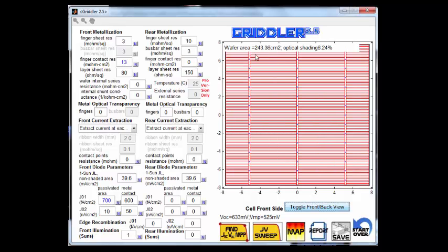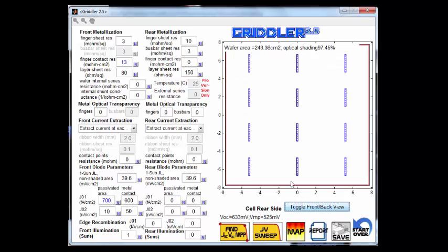And that's pretty close to what you would get if the cell were measured under an IV tester, with probe bars aligned to the bus bars, each probe bar carrying 15 contact pins to make contact to these 15 current extraction points on the front bus bars. And then on the rear, there would also be contact pins that are specifically making contact to the solder pads.